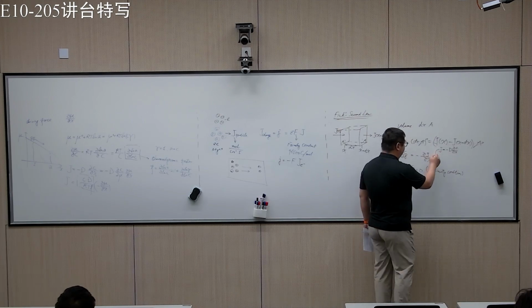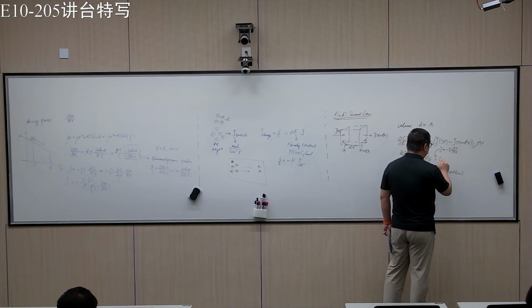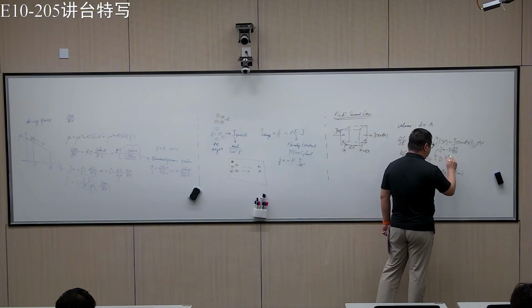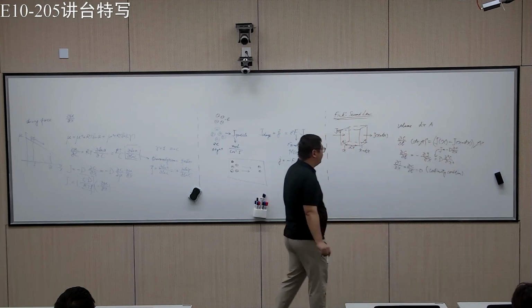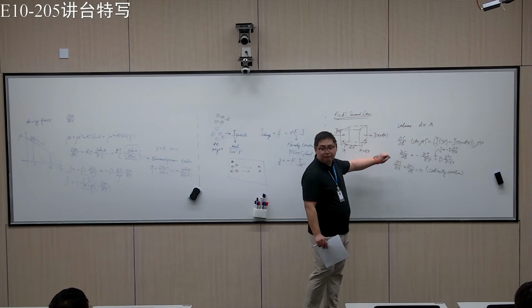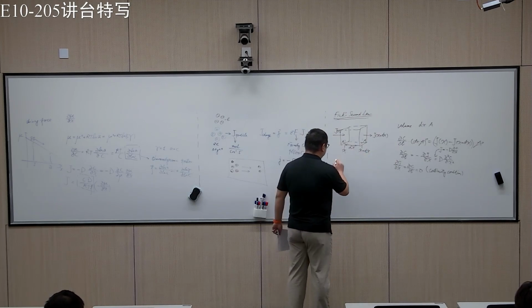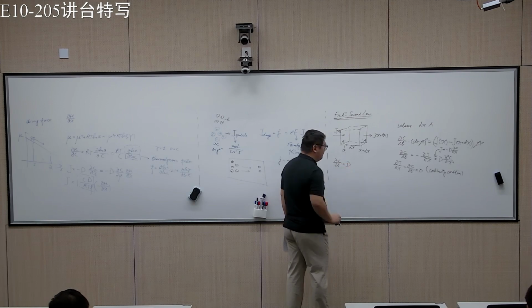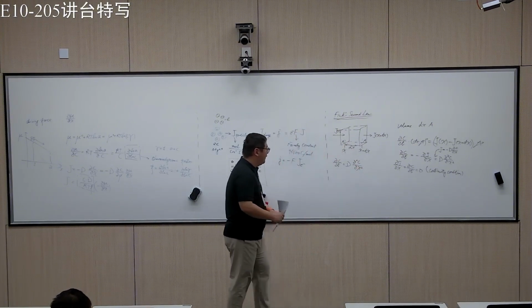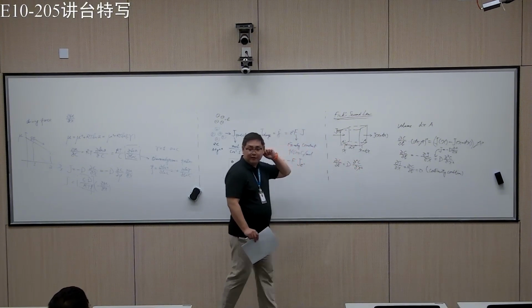If I plug this in, the negative sign cancels out, and you have another derivative. So this is the most common form of Fick's second law: partial C, partial t equals the diffusivity times the second derivative of C with respect to position.